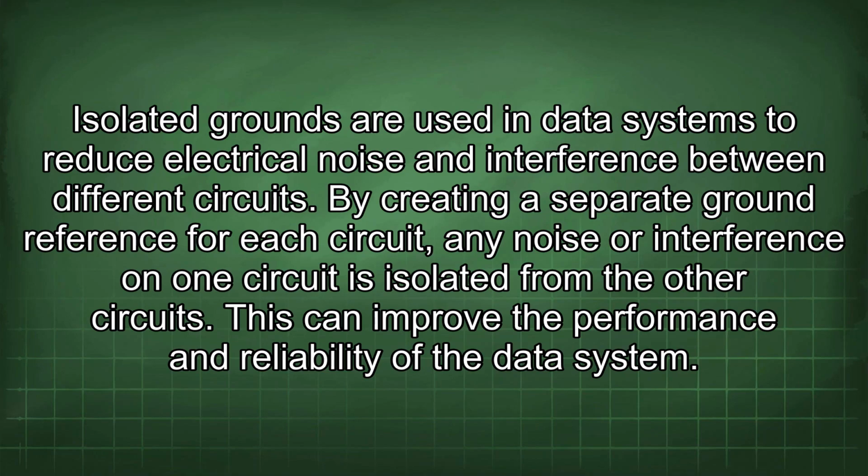Isolated grounds are used in data systems to reduce electrical noise and interference between different circuits. By creating a separate ground reference for each circuit, any noise or interference on one circuit is isolated from the other circuits. This can improve the performance and reliability of the data system.